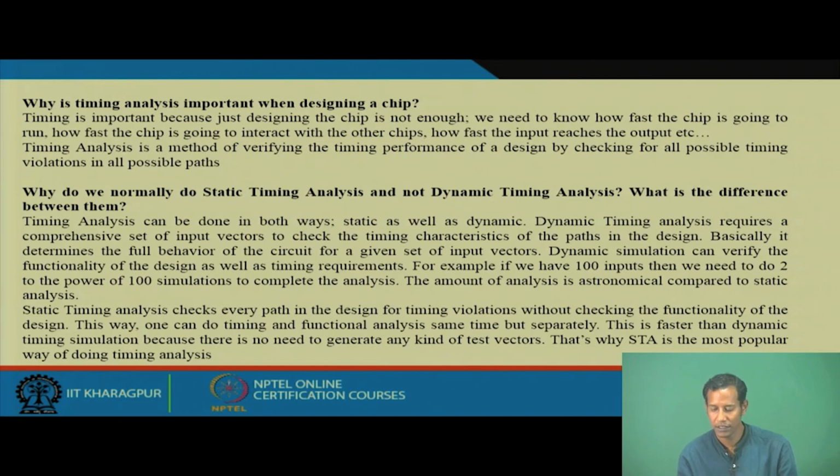Dynamic timing analysis requires a comprehensive set of input vectors to check the timing characteristic of the paths in the design. Basically, it determines the full behavior of the circuit for a given set of input vectors. Dynamic simulation can verify the functionality of the design as well as the timing requirements. For example, if we have 100 inputs, then we need to do 2 to the power of 100 simulations to complete the analysis, and the amount of analysis is astronomical compared to the static analysis.